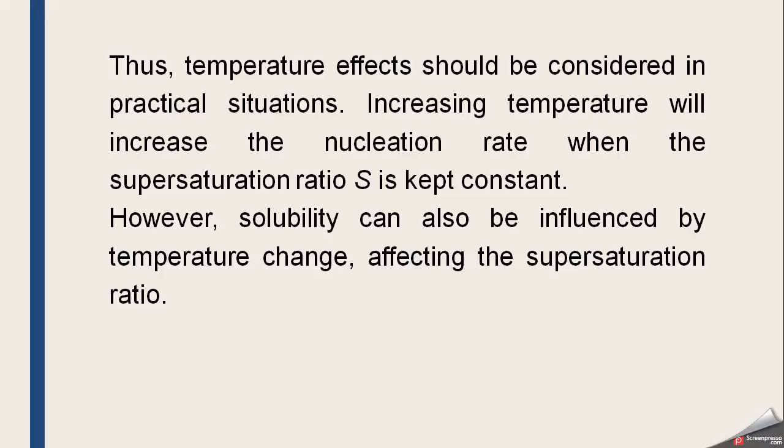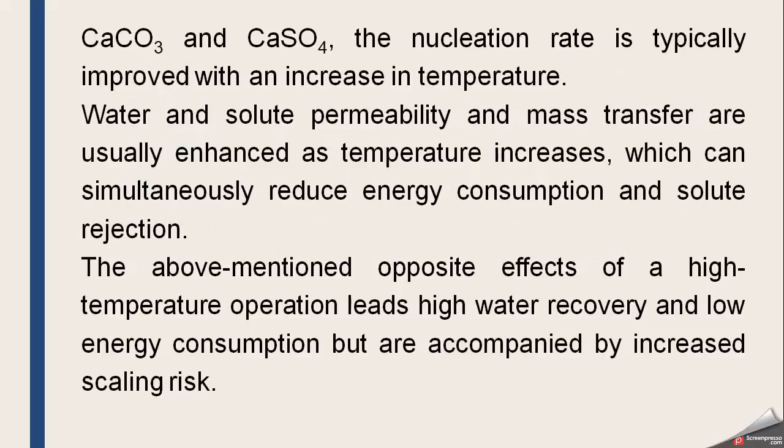Maybe in some cases temperature increases the solubility, and in a few cases by increasing the temperature the solubility decreases, and this is an interesting phenomenon. Now for calcium carbonate and calcium sulfate, the nucleation rate, that is, when crystal formation starts, is typically improved with an increase in temperature, and water and solute permeability and mass transfer are usually enhanced as temperature increases.